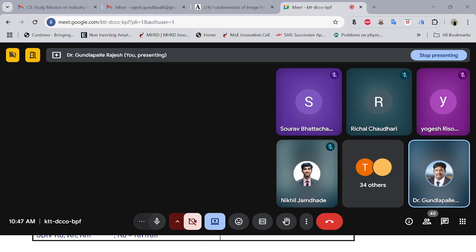Rn will contain a 32-bit value, and this 12-bit immediate number will get added to Rn and loaded into RD. You can find this application while handling special function registers.